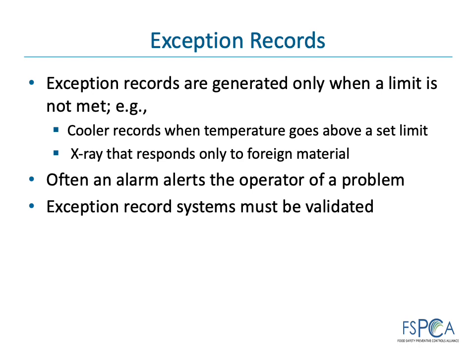Such systems must be validated and periodically verified to ensure they are working properly. With such systems, monitoring records may not always be necessary when validation and periodic verification are conducted to ensure that the system is working properly. Therefore, records of refrigeration temperature during storage of food that requires time/temperature control to significantly minimize or prevent the growth of or toxin production by pathogens may be affirmative records demonstrating temperature is controlled, e.g., a chart recorder, or exception records demonstrating loss of temperature control, e.g., an alarm system that records when a deviation occurs.